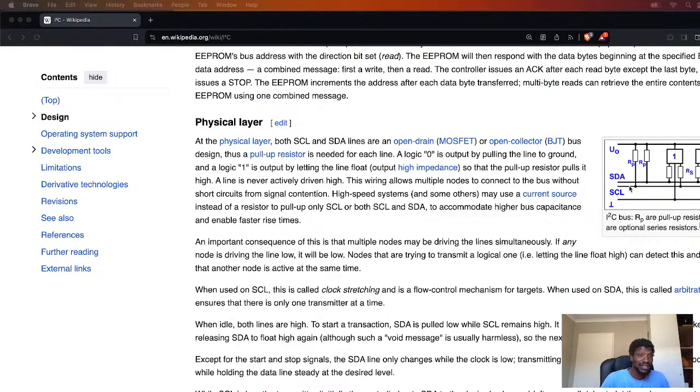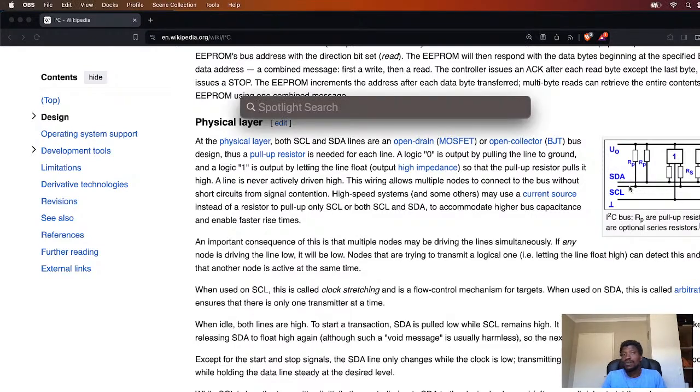SPI is much faster, we have much higher throughput, and the fastest SPI can go is determined by the fastest clock you can use, and I think the least you can divide it by is 2, so you could get up to quite high data rates. Okay, and then I2C, we've covered that it supports auto acknowledgement and auto non-acknowledges, so that's good.